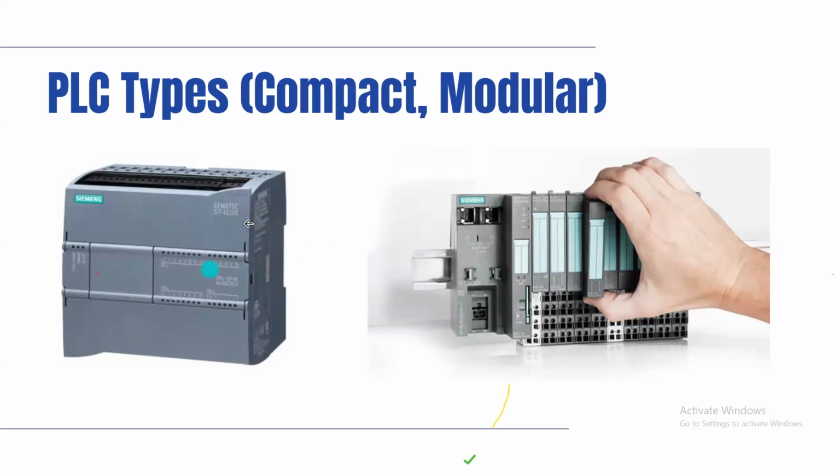For example, these are Siemens 1200 PLCs. Some of them are compact PLCs, which means they have the CPU, power supply, IOs, and everything embedded on them. But there are some of them that are expandable, which I will try to show later. So they play in this medium range where you can have it as a compact PLC, where you know exactly what you need for your requirements.